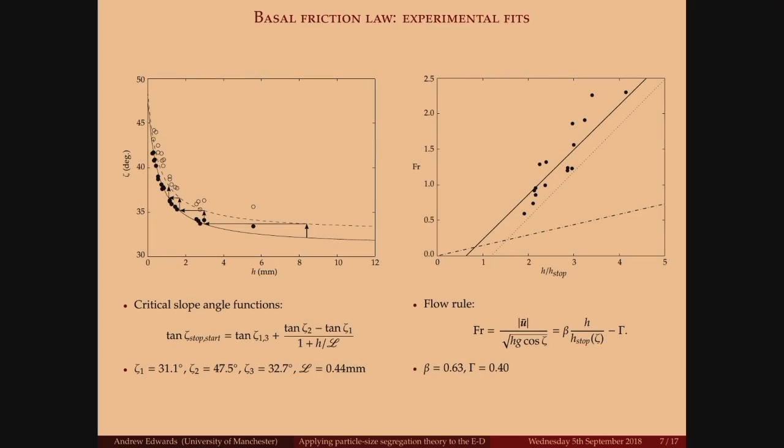So our friction law is based on the work of Pouliquen. To measure the parameters for our setup, you have to perform a few experiments. First of all, we measure the thickness of a deposit that's left by a steady uniform flow, which we call h_stop, for different slope angles. And for this h_stop, you then incline the slope and record the greater angle before this flow begins to flow spontaneously, which is called h_start. If you get these two curves, you have a range of friction angle parameters.